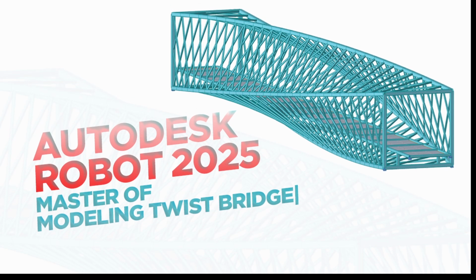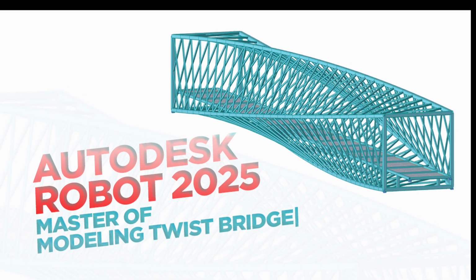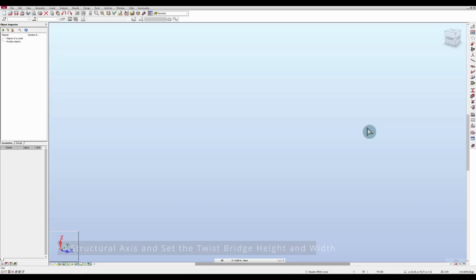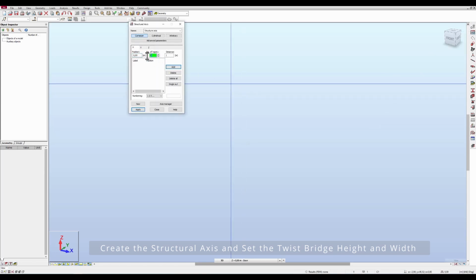Create the structural axis and set the twist bridge height and width. Learn how to create a structural axis as the basis for the columns and beams grid. In the structural axis dialog box, on the X tab, set the position to 0, number of repetitions to 30, distance to 1.5 meters and numbering to 1, 2, 3, and then click Add.